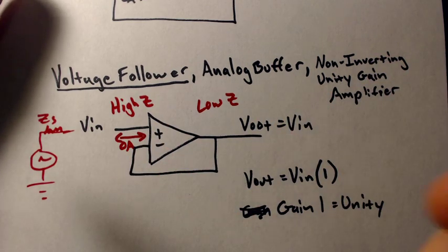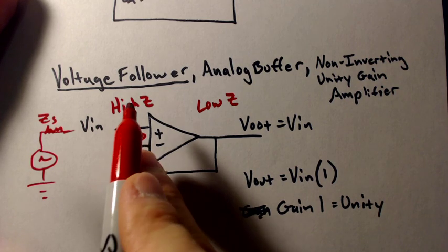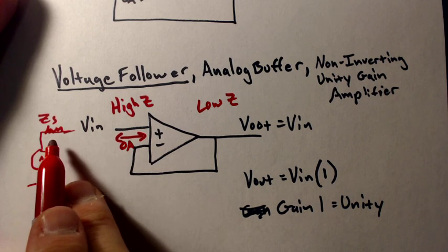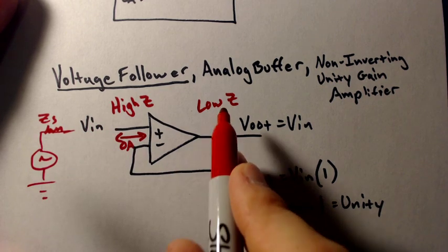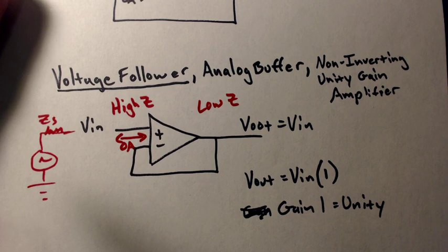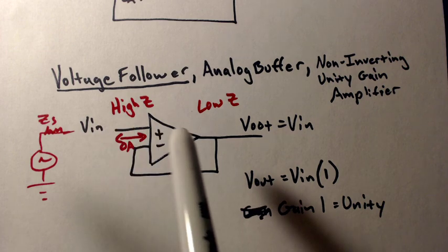in most configurations, you don't have to worry about that anymore. All of a sudden, the impedances are negligible because the inputs are considered to be sufficiently high that they have little to no effect on this voltage over here. So you don't have to calculate that. Same thing with the output. We can consider the output to be sufficiently low enough impedance that it doesn't matter. Okay? So that's really kind of the benefit of this voltage follower. And that's why I end up using them so often and in every single design I've ever looked at, because it solves that problem.